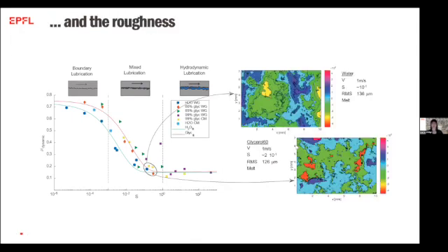So what is interesting is that if we look at the full surfaces after deformation, and we went to the profilometer, we measure the asperity size. We see that in our mixed lubrication condition, the asperities have an RMS of about 126 micrometers at the end. This is much bigger than what we had at the beginning, and this is because our asperities melted during deformation. So that means that we were really under mixed lubrication condition, because part of the load was still supported by the asperities, and we can have frictional heating at the asperities, and melting, and increasing of the asperity size.